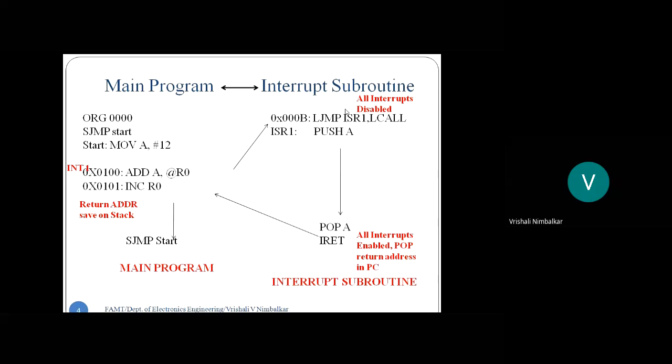We do this modification because the gap between two interrupt vector addresses is very small, and the interrupt subroutine cannot fit within those 8 memory locations. So that's how the modification is done. Is that okay? So when we do our LED blinking program today, we will do it in this way, right?